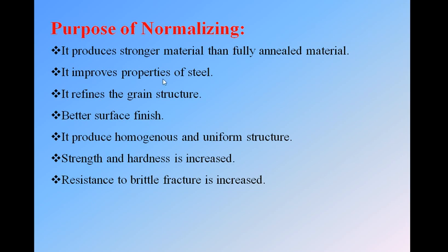It refines the grain structure. Grain structure means there is a change in crystal structure, because up to 910 we have the BCC structure, and above 910 we will have the FCC structure. So there will be a change in crystal structure at temperatures above that.